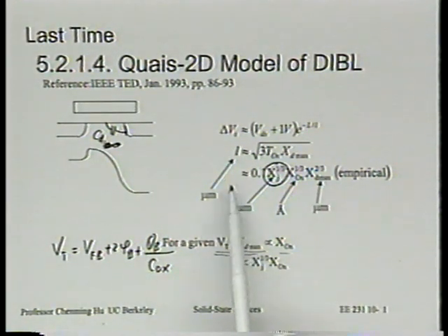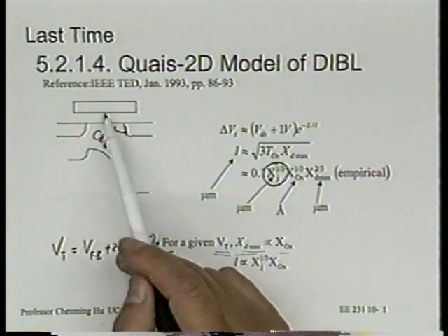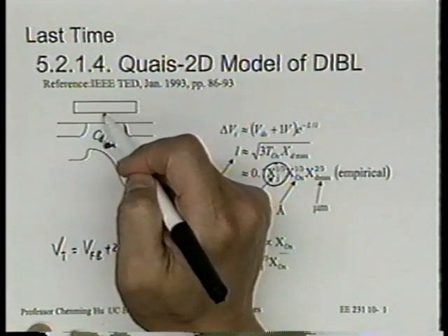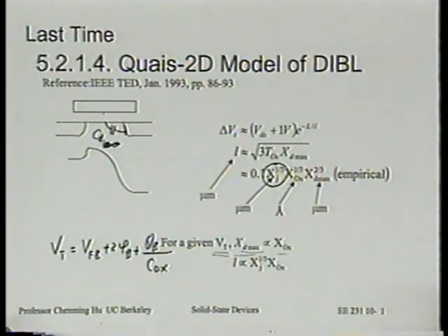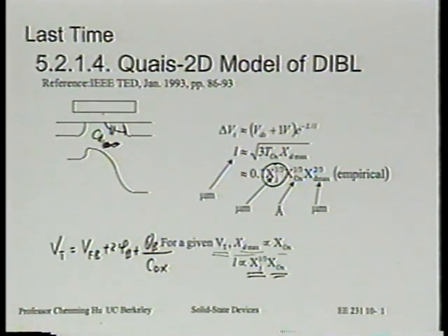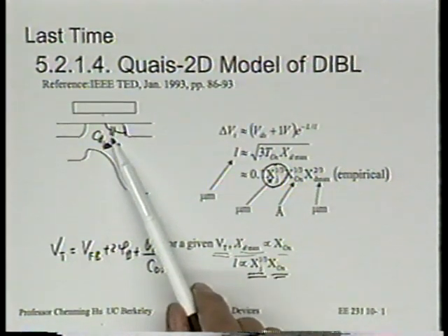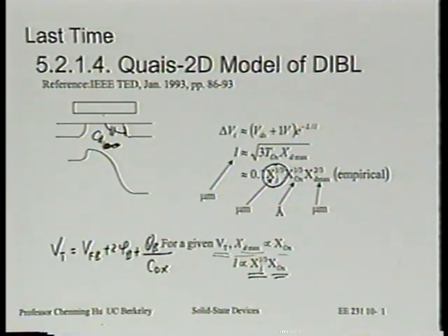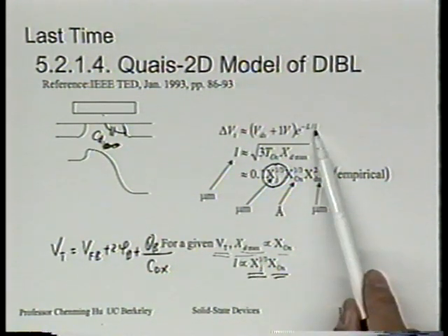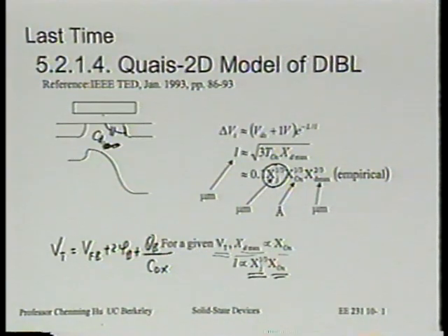So the effect of the junction depth is not the same as the effect of oxide thickness. It's weaker. Let's not get into more of that, but I just want you to remember this useful relation: xj to the 1/3, oxide to the 1 power. The model I suggested, thinking of these three capacitors fighting against each other, is a very good model, but watch out for the pitfall of thinking that there's a linear dependence on L, or some kind of linear dependence on xj. The fact that this 1/3 power of xj shows up in this exponential term means it's still a very strong function of xj, of course. It's just not the same as oxide thickness.